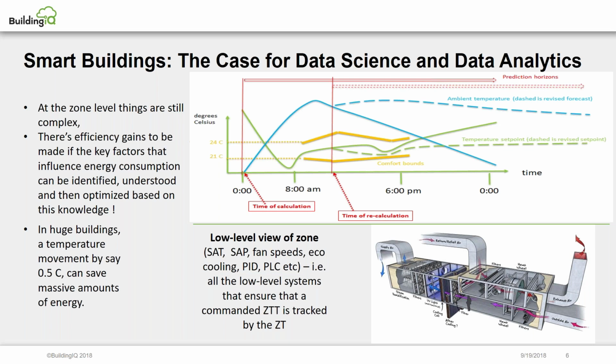So in that example, again, referring back to this example over here, if you start at time 0, we have a forecast, which is the blue. We have a forecast of the outside air temperature, how it should look. And then what we do over here in this example, we cool down the building when the energy price is low. And during the time when the building operation starts, we let it drift.